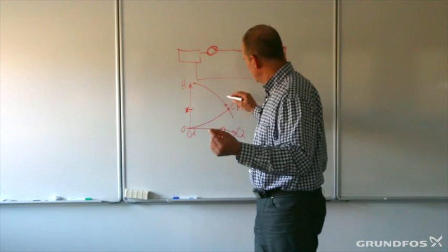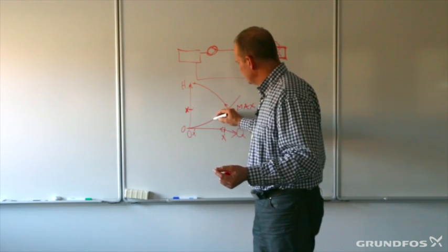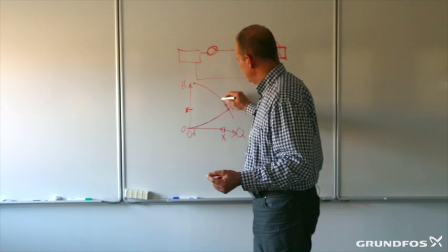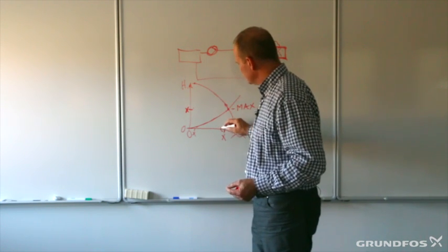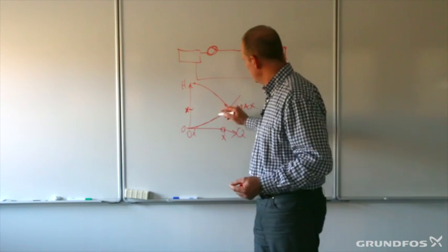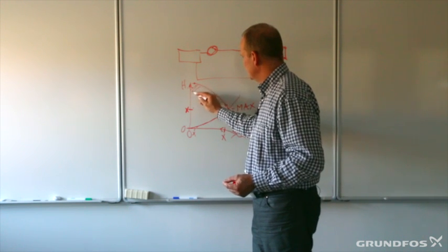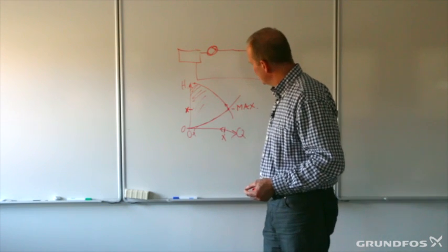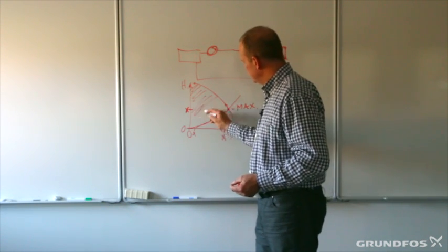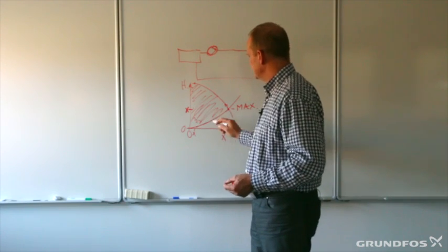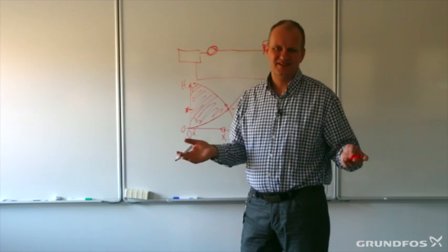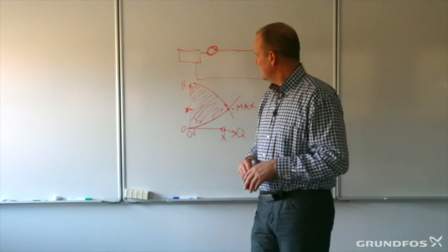So what we can see is that a fixed speed pump does the exact opposite thing of what it should do, as it would be more optimum to follow this line, but instead it increases the pressure. So as we go along to zero flow, we simply just increase the problem and deliver more and more differential head. So all of this here, you could say, is actually equivalent to wasted energy.